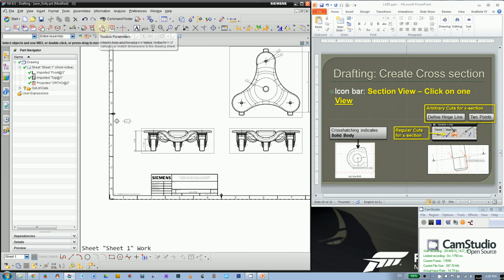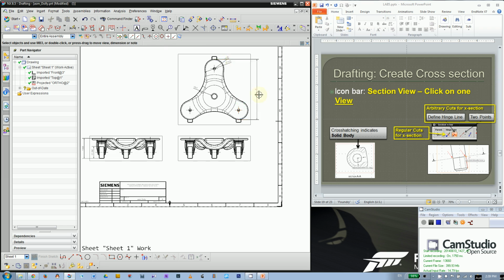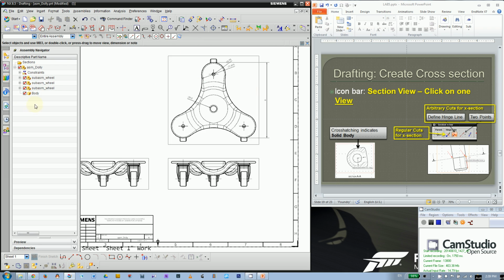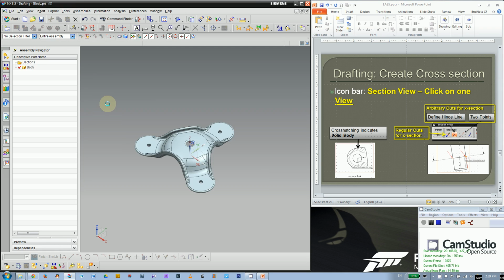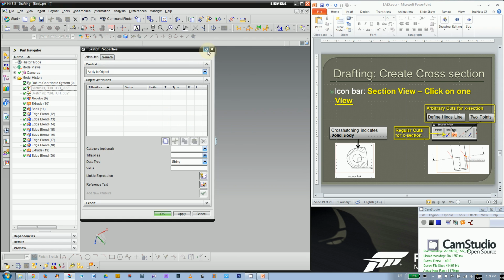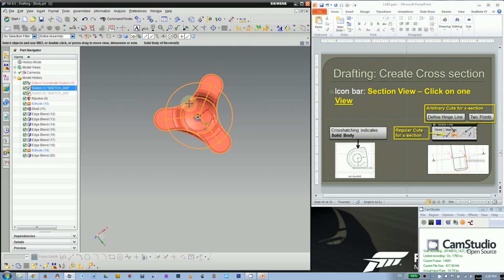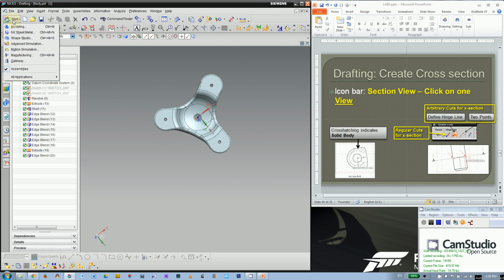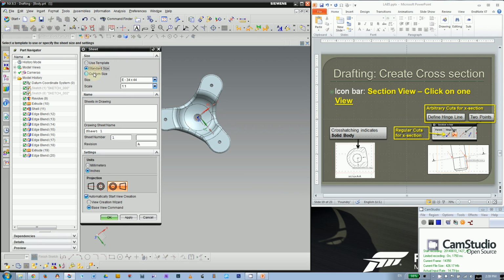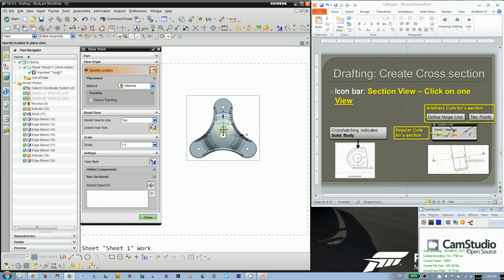All right, and, okay, remember in Sketch you have a lot of dimensions, right? Let's make this the displayed part. So for this part, in the Sketch, we already have a lot of dimensions. And when you do the drafting, okay, so we're still in drafting. We can go back to modeling, then go to drafting. You ask for paper size. Try size C. This time no template. Base view command. Then put it down.